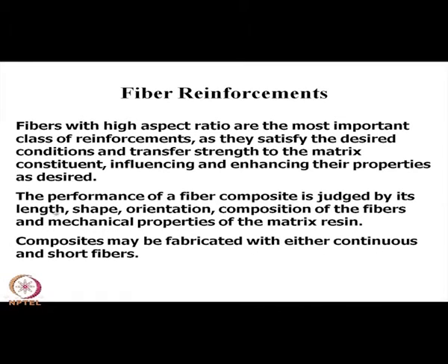So, the performance of a fiber composite is judged by the length, shape, orientation and composition of the fibers and the mechanical properties of the matrix region. If the surface area of the reinforcement is very high, the properties of the composite would be very high, strength properties would be very high. That can give very good synergism, synergistic properties can be available.